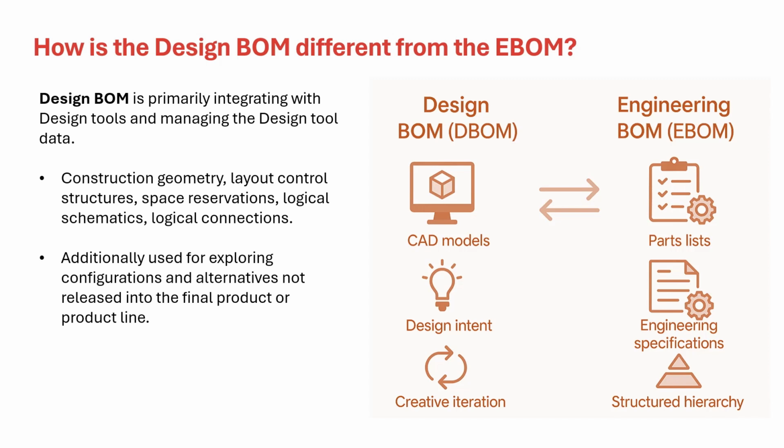Whereas the EBOM is a list of all the parts and sub-assemblies that include software parts, electrical, electronic, mechanical, or documents. It will also include colored parts, alternates, and substitutes. It can also include non-geometric parts like sealants and lubricants or packaging. Also, the EBOM will be a buildable configuration with the help of rules and constraints.